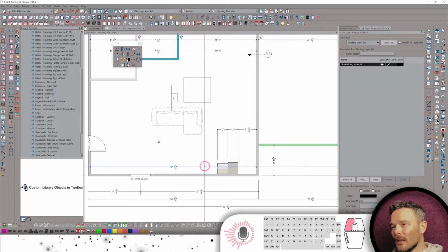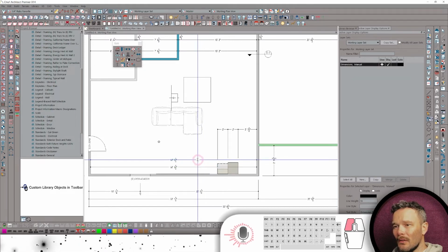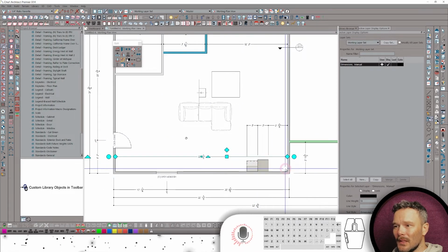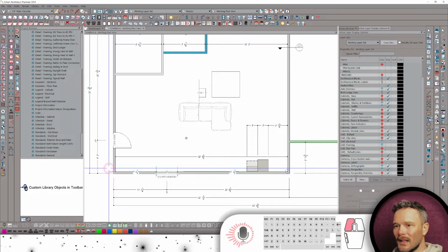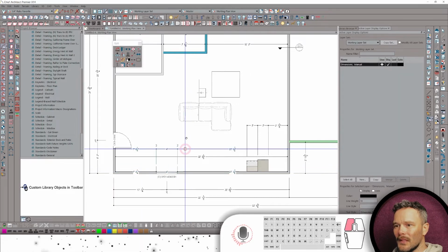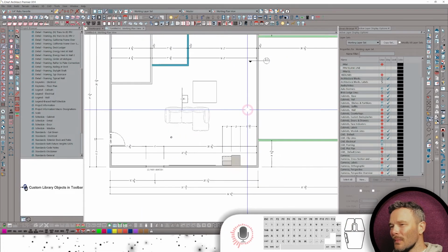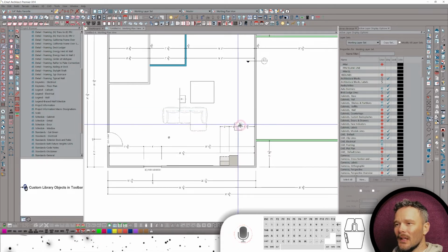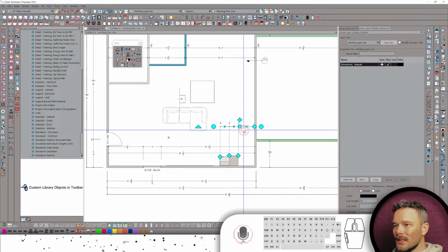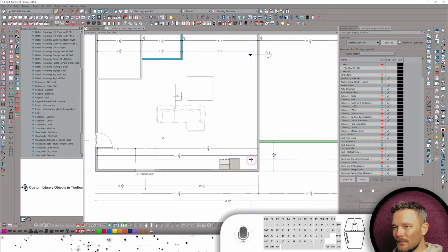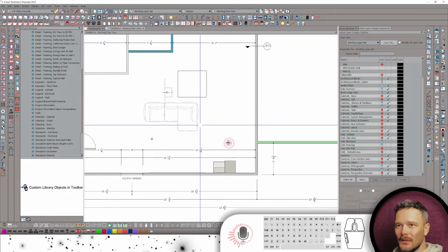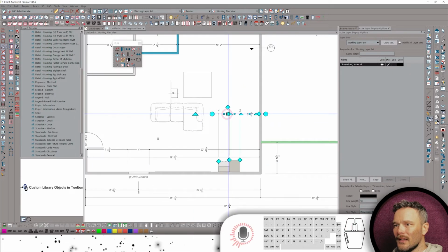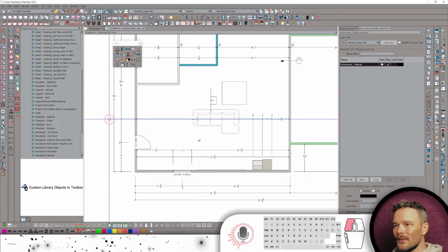Now, something that's true of all my dimension defaults, they need to be very accurate. You need to be very close to what you're measuring. You notice there, we didn't pick up that window. But if we do that in manual dimension again and run it right next to that window, it's going to pull that window dimension there. So all of my dimension defaults, you have to be very accurate about what you're dimensioning to. So oftentimes I may dimension to these cabinets per se with that interior dimension tool, right? And then maybe I want to come up here and continue on through like this.